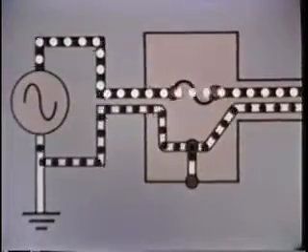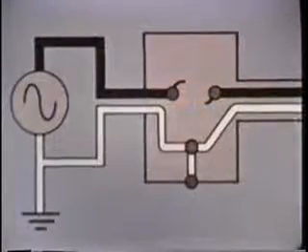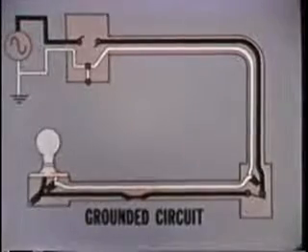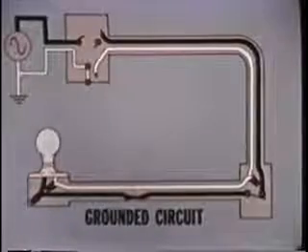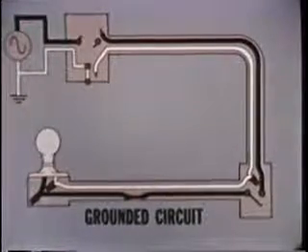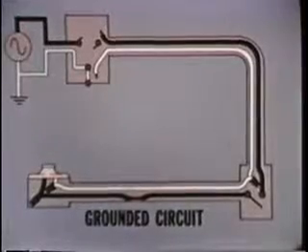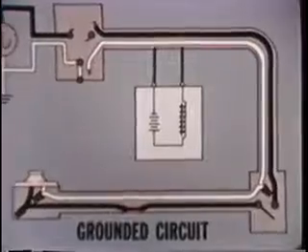Let's examine another case where we come on the trouble site to find a blown fuse. Once again, to deal with the circuit safely, remove the wires from the power source. Remove the other elements in the circuit by opening the switch and removing the bulb. This time, instead of using a multimeter, let's use a buzzer-type continuity tester.